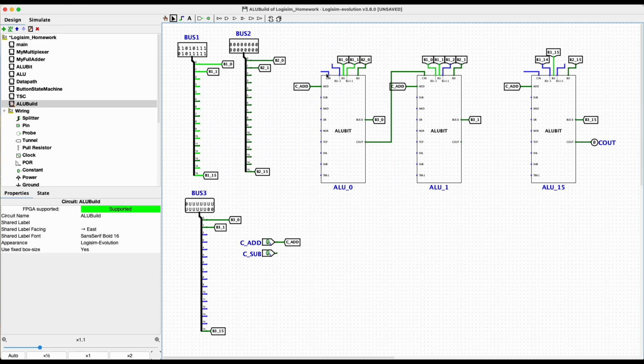Well, remember when we're taking the 2's complement or subtracting, that we've only inverted the bits and we never added 1 to the least significant bit. And the least significant bit is bit 0 right here. So when we're subtracting or taking the 2's complement, then we want this to be high, turn this voltage to high, and that'll do the add 1 right there.